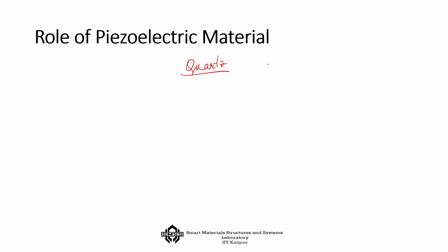That means if you have a quartz, let us say, like this, and you are exciting it with some kind of a force, it is going to create a V sin omega t. So, force creating voltage, and if this is of omega frequency, you are going to get an omega frequency in terms of the electric voltage. So, it will be a regular electrical signal out of it.